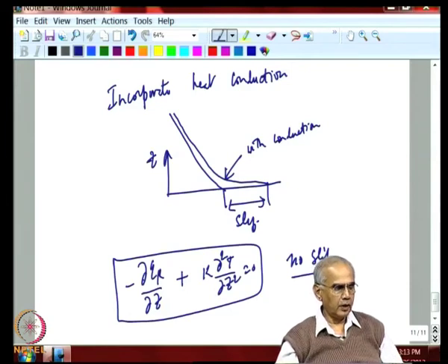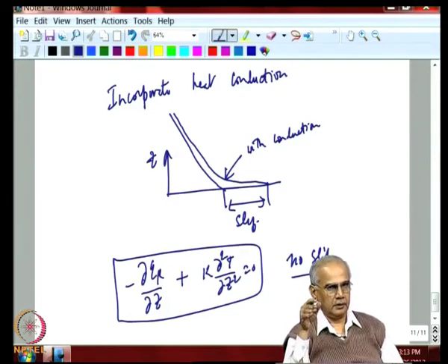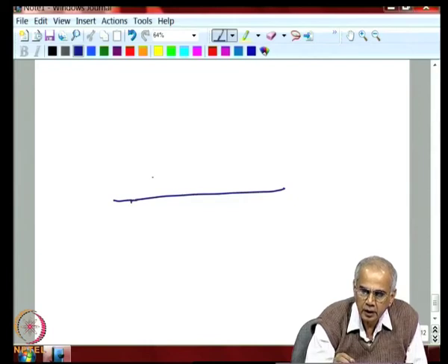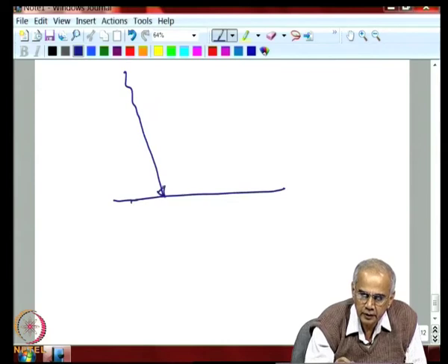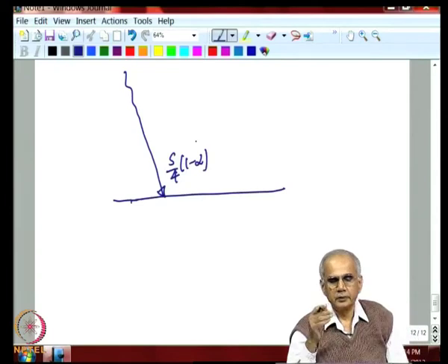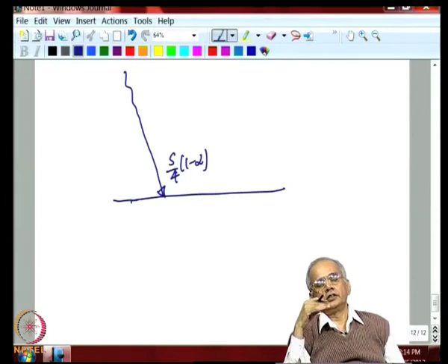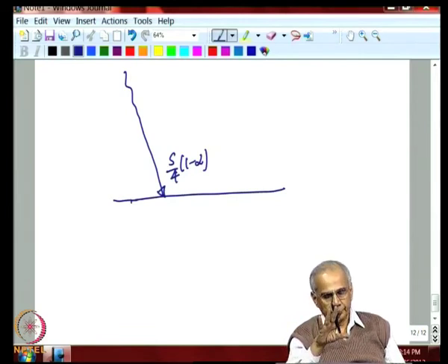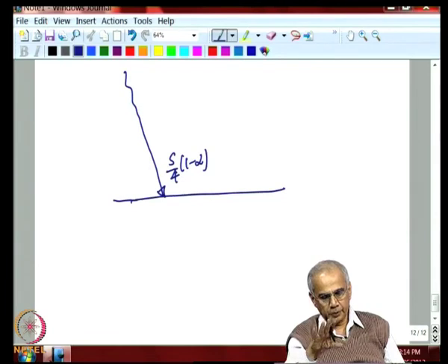Now, we want to relate the heat flux by conduction and by radiation to what is coming in. So, we have a simple model of the Earth's atmosphere, neglecting the absorption of solar radiation by the atmosphere. What is coming in is really S by 4 into 1 minus alpha, that is the incoming solar radiation. After energy is lost by reflection to space, all the remaining energy we are assuming is not absorbed by the atmosphere, but by the surface.